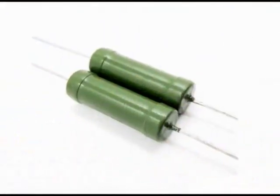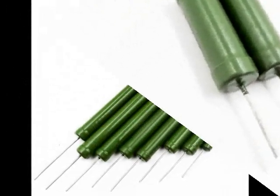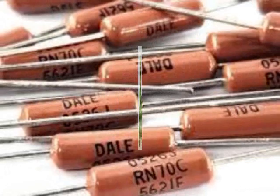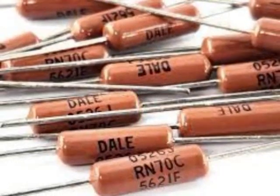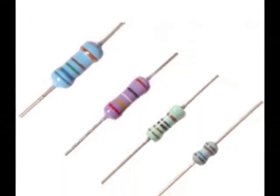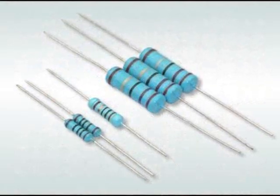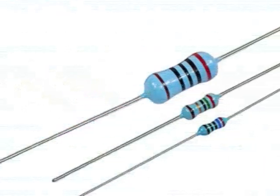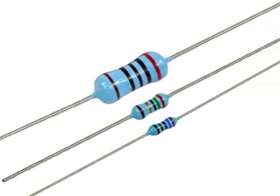Metal film resistors are made in E24, 5% and 2% tolerance, E96, 1% tolerance, and E192, with 0.5%, 0.25% and 0.1% tolerance. The tolerable power of this type of resistors is from 0.05 watt to 0.5 watt. In general, film resistors and especially metal film resistors are used in low consumption applications.